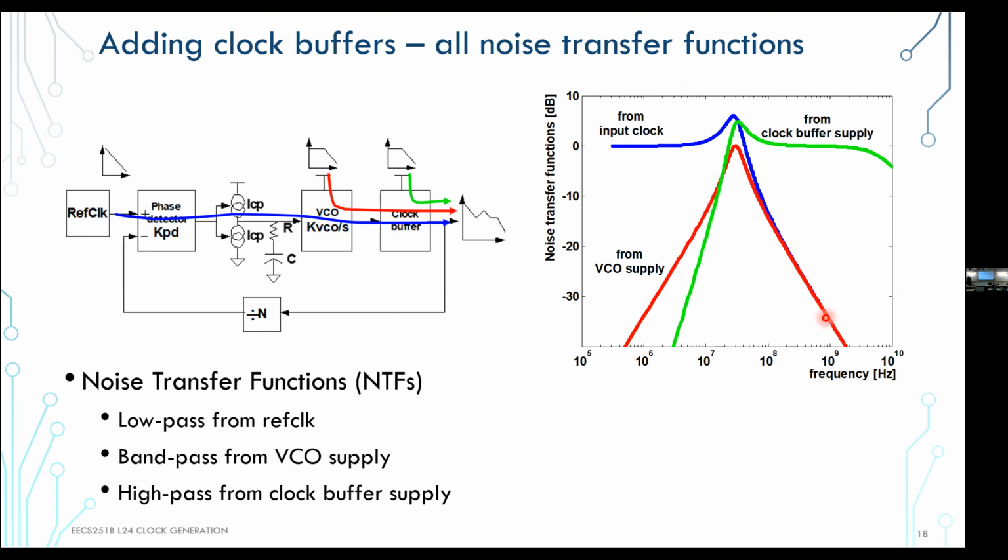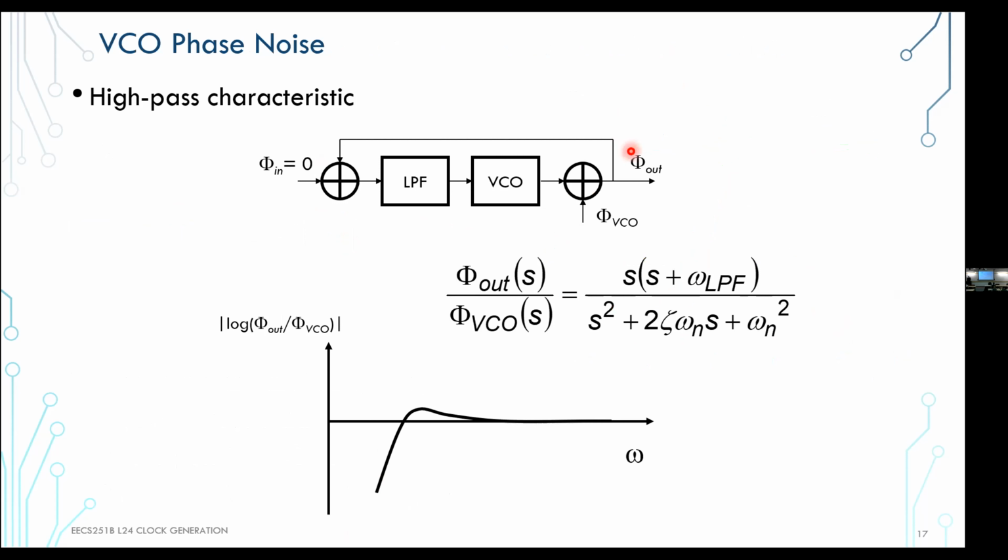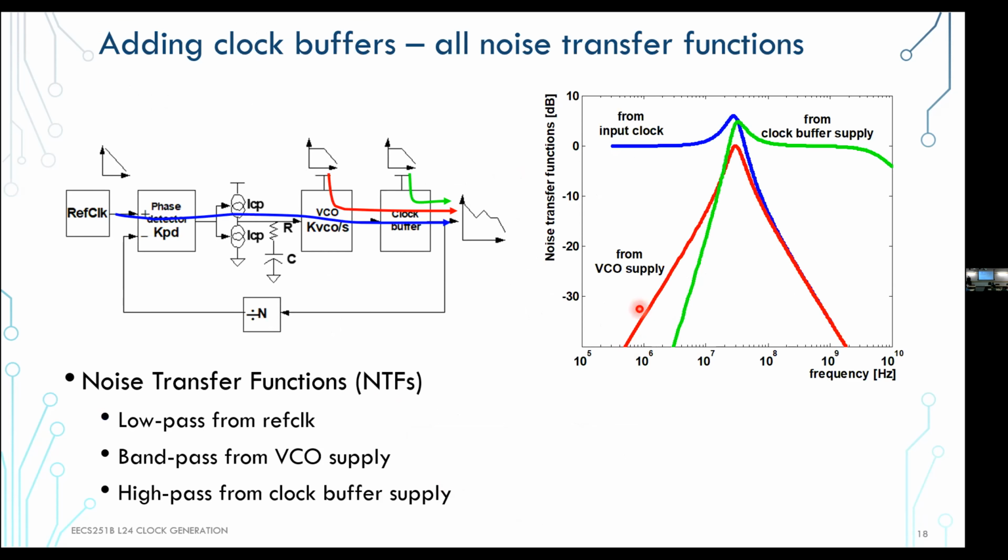So you normally have this transfer function from the VCO output to the PLL output, and you need to multiply it. If you're now projecting what happens from the supply input of the VCO to the output, there's an additional 1 over S, or K_VCO over S transfer function. It's not going to be exactly K_VCO, it's going to be some K_supply-VCO over S, but it's still going to be some impact of the supply on the VCO phase. And that's going to have an integral, 1 over S curve. So you multiply these two, and you will get a shape that looks like this.